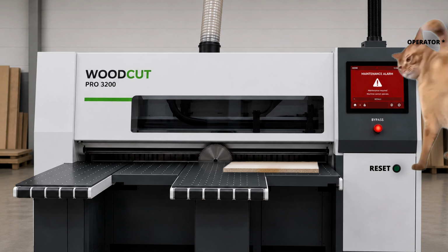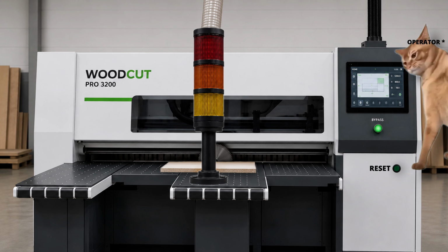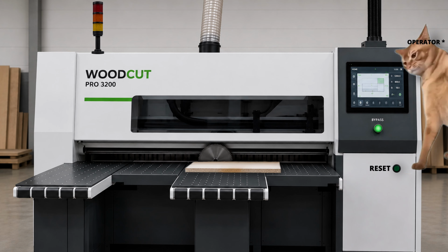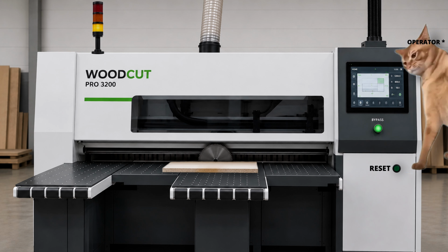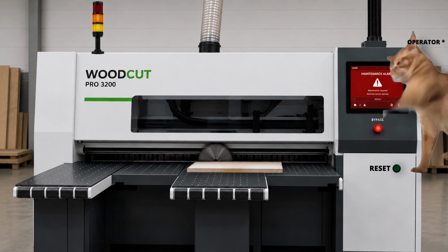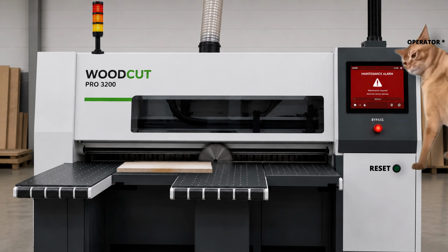So to resolve this issue, we are going to mount a lamp indicator on the machine which has three colors: yellow, orange and red. Whenever the machine generates its first maintenance alarm, the yellow lamp will start to glow, and whenever the machine generates the second maintenance alarm, the orange lamp will turn on.